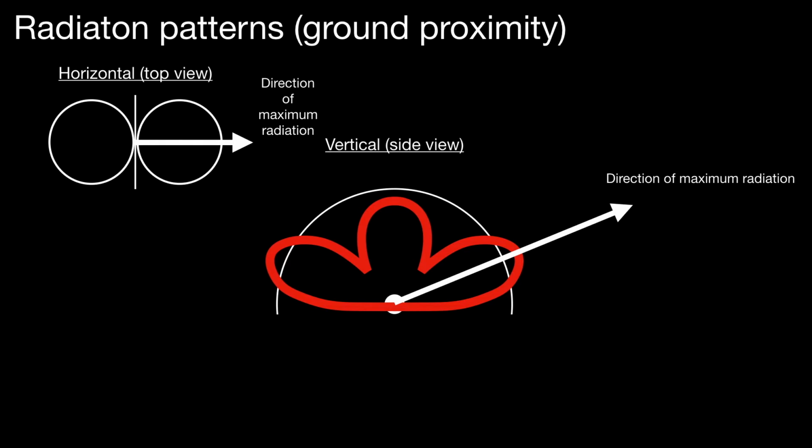So what we've said here is that there is what you might imagine the ideal to be, that semicircle, as the ground has risen up, but in fact the influence of the ground on the propagation of the signal itself modifies the radiation pattern on the side view, and the lower you get, the higher the angle of maximum radiation.